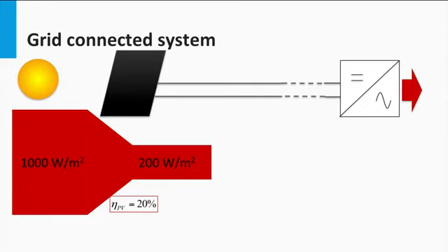Depending on the length of the cables and the amount of current through them, this loss could be anywhere around 1 to 5%. In this example, let's assume that we have a cable loss equal to 2% of the PV power production, or equivalently the cables have a transmission efficiency of 98%.